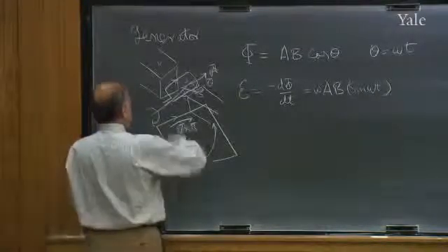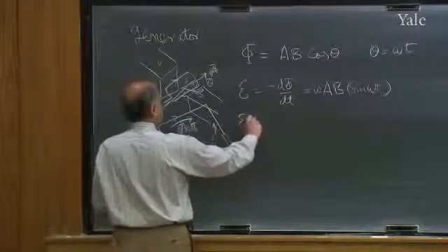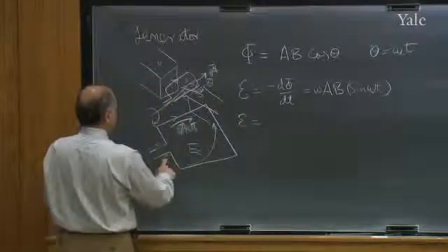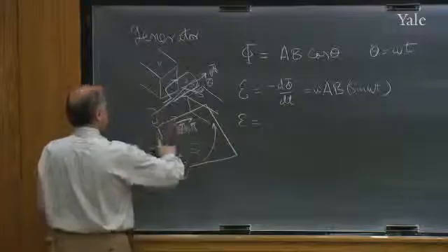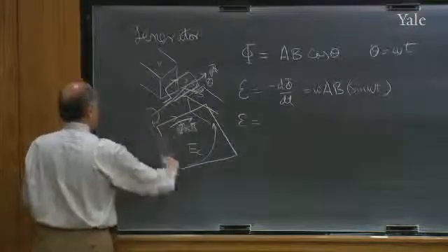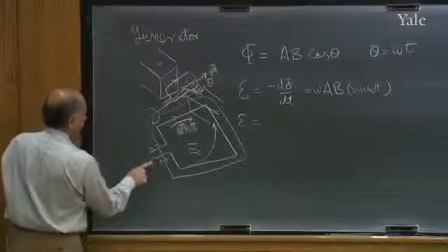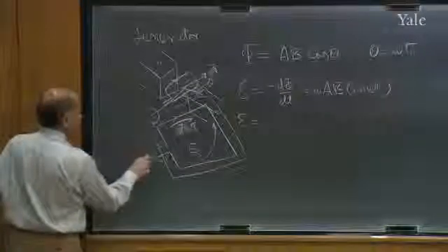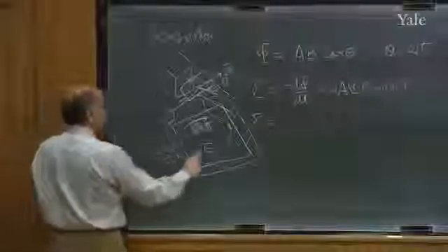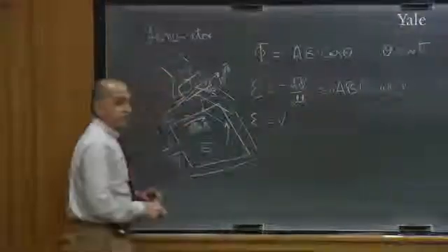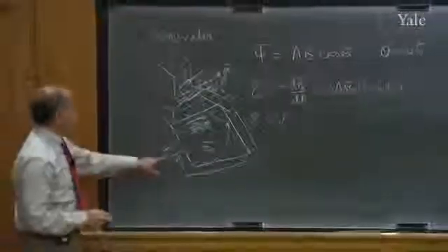And the line integral of the v cross B, which is the EMF, will numerically equal the integral of the electric field from this terminal to that terminal. But now, if you put the whole thing in a box and you don't know anything and you come outside, what you will find is this will be positively charged, this will be negatively charged, and there will be a voltage between these two, which will numerically equal your EMF. This will be that polarity.